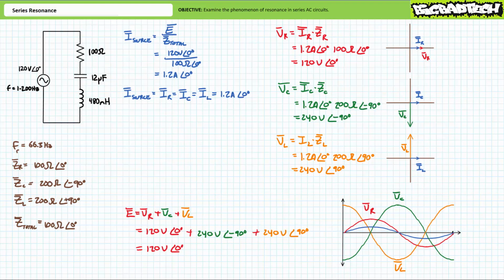The key to the resonant condition is of course accounted for by the equal and opposite natures of the reactive capacitor and inductor. Given voltage across the capacitor has a phase shift of negative 90 degrees and voltage across the inductor has a phase shift of positive 90 degrees, they are plus or minus 180 degrees, or completely out of phase with one another. When voltage across one reactive component peaks, the voltage across the other reactive component valleys and vice versa. What's really happening at conditions of resonance is that reactive power is pulsating back and forth between the reactive elements inside the circuit. Sometimes this internal interchange of reactive power can be surprisingly large, as in this example circuit.